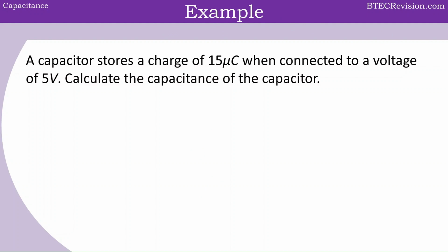Now, let's look at an example. A capacitor stores a charge of 15 microcoulombs when connected to a voltage of 5 volts. Calculate the capacitance of the capacitor. We can start by writing down our equation. Capacitance equals charge divided by voltage.